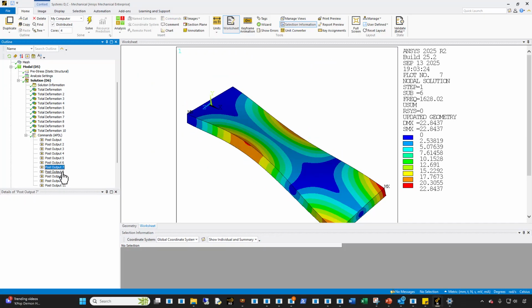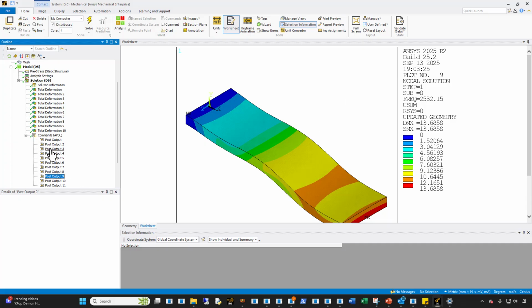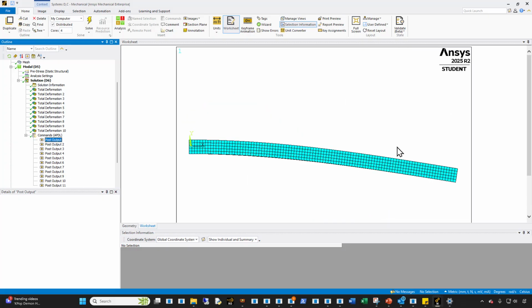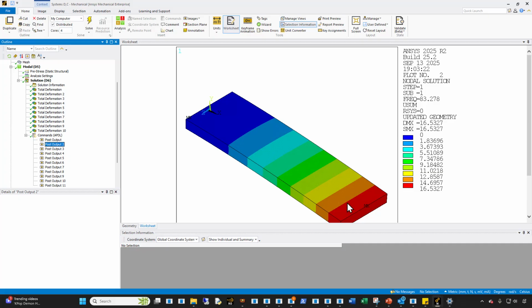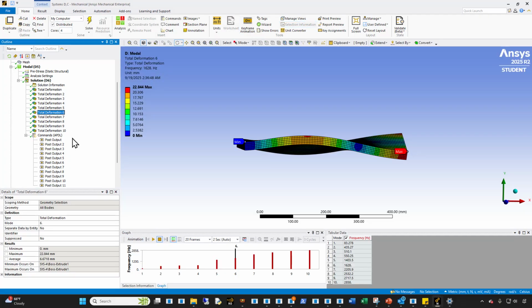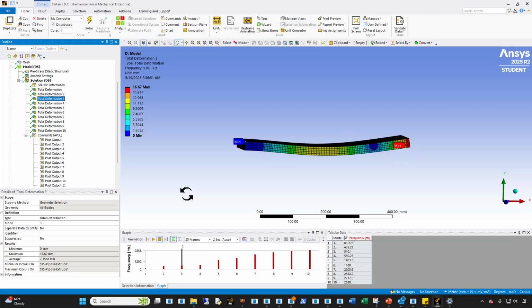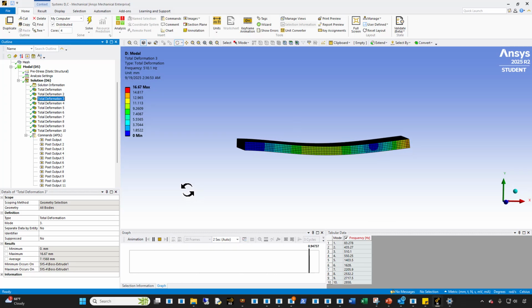And then you can see in this case, you can't really do the mode shape display anymore in this view, but you can see this is what it starts with, and the deformed shape is in a bend shape. And this is one of the limitations with Mechanical in a pre-stress analysis, that you really can't see the actual mode shape.